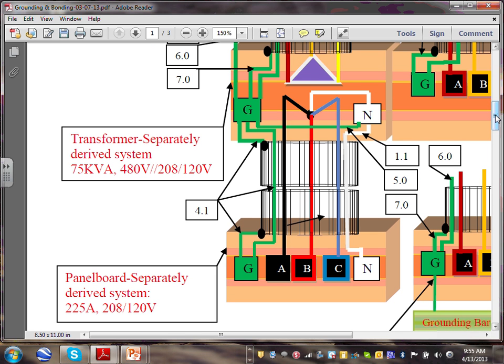That's bonding the panel enclosure into that transformer enclosure. You have to bond the conduit through a wire going between them, or you can have conduits and you have to bond the conduits from both sides, typically through a wire, because we use a flex in between them.